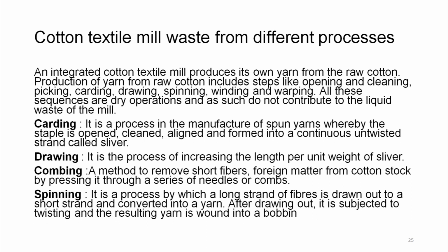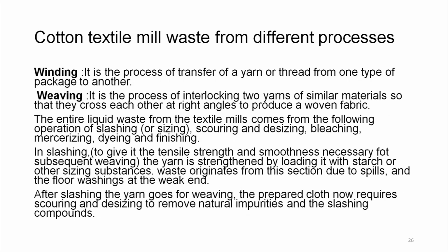So, there are many methods. They may not be contributing to liquid waste, but they are contributing to solid waste in the cotton mill. Then comes winding. It is a process of transferring the yarn or thread from one type of package to another. And then comes weaving. It is a process of interlocking two yarns of similar materials so that they cross each other at right angles to produce a woven fabric.